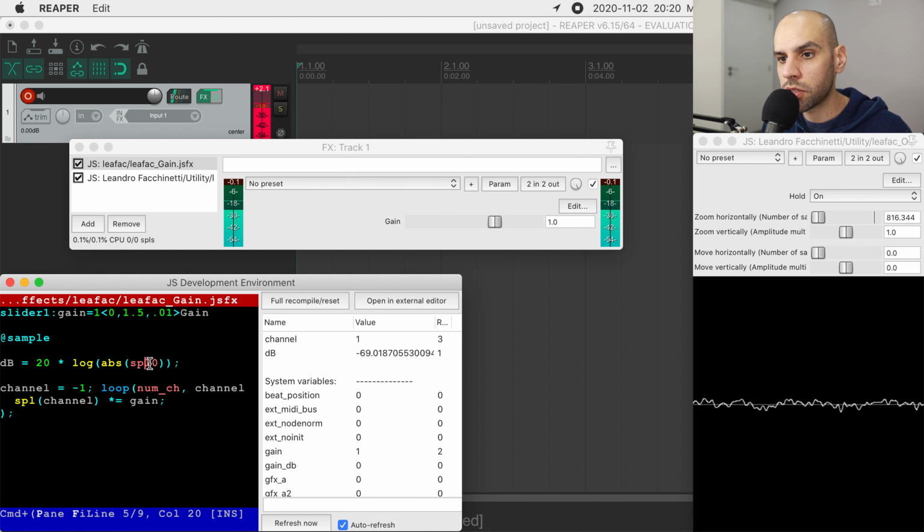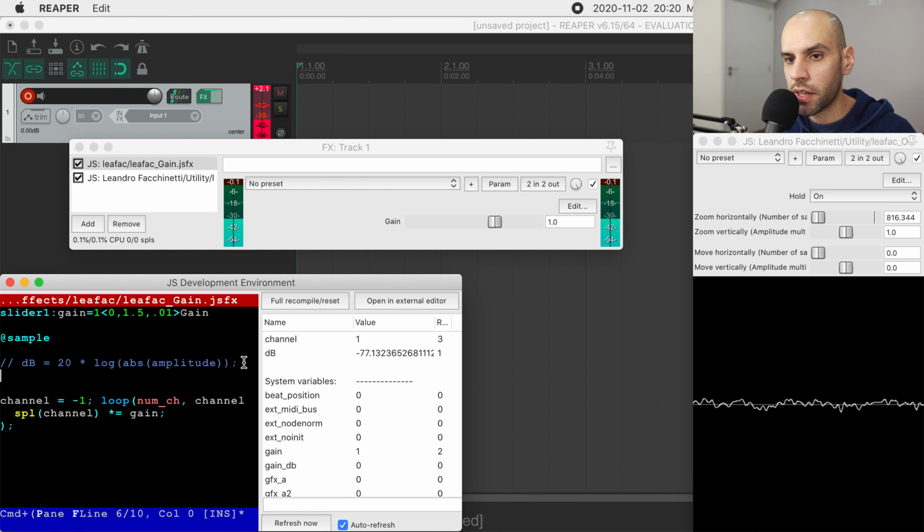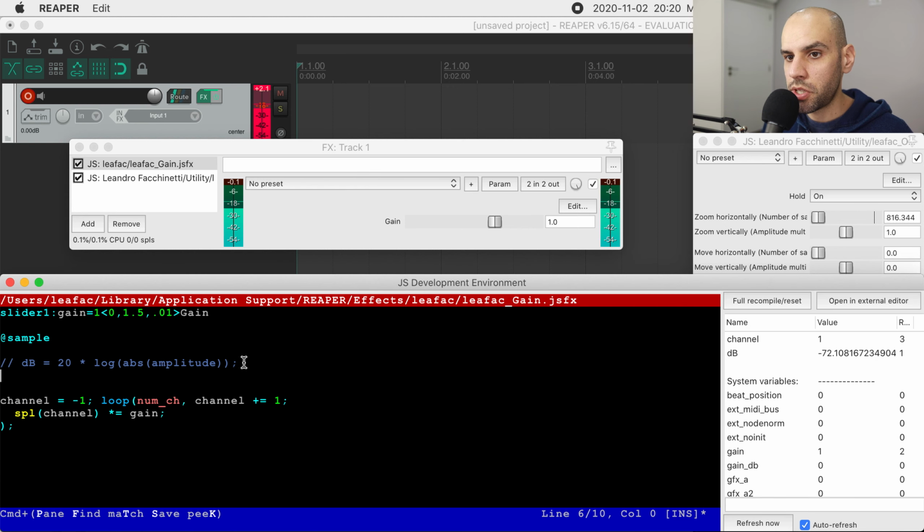Let's take a look at how, so I'm just going to say amplitude. Just so you have this here on the screen. Now let's take a look at the opposite, which is going from dB. And how do you get to amplitude? Well, you just do the opposite, right? So first here, this 20 that is multiplying goes to the other side of the equal sign as division, right? And then this log, that's log base 10. So you just take 10 and you elevate everything by 10.